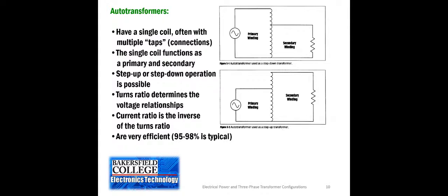Now, one reason that delta is good is that delta connection is more reliable. A common delta will still function if we disconnect one of the coils, or if one of the coils burns out. The other two coils will keep all three phases energized. And we call that an open delta. You'll see those little connection points at the bottom of those diagrams. The power comes in, and then the voltage comes out.